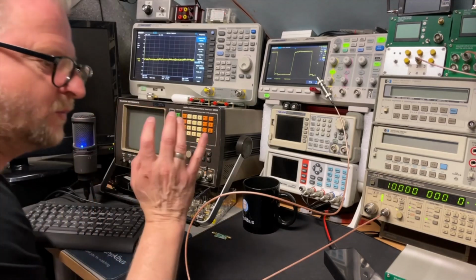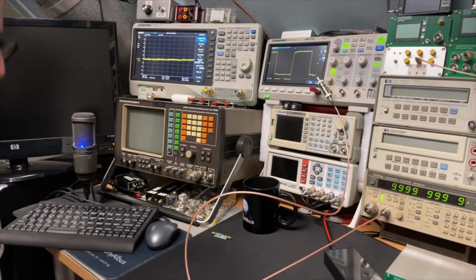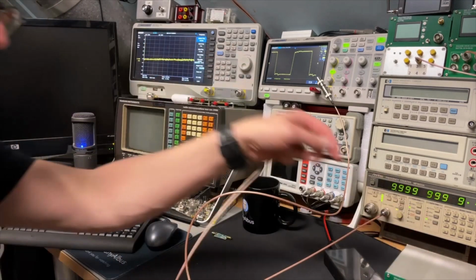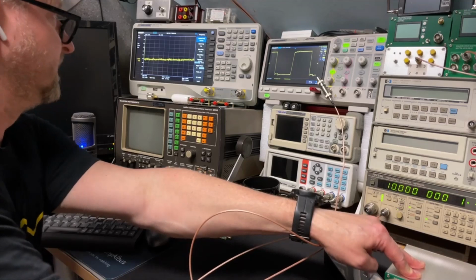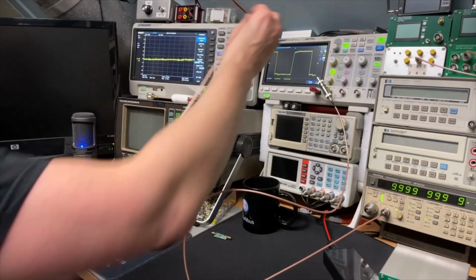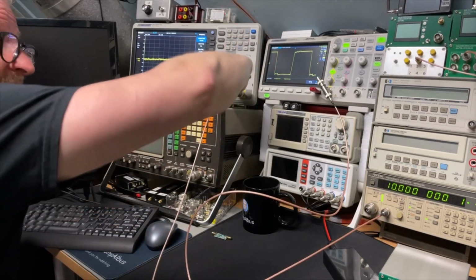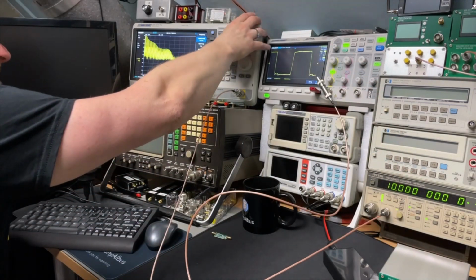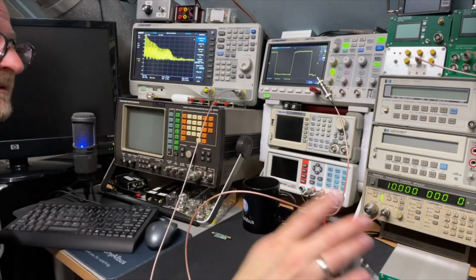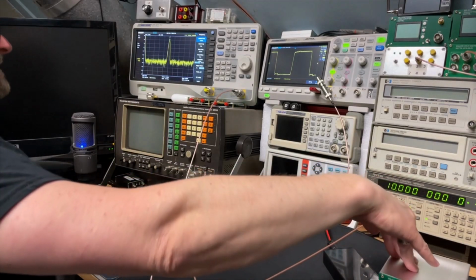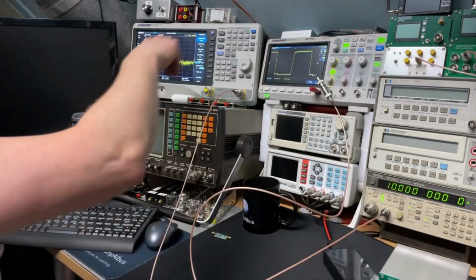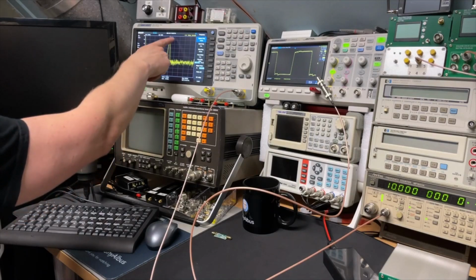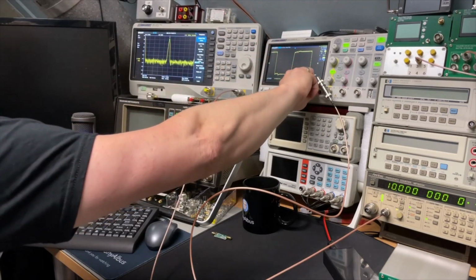Then why would you not want to use this as a distribution amplifier? I just want to do that, but some people don't, and I will explain why. Because it is for a wide frequency range, it means that the filtering is not that good. If you look here, it is a very nice wave.